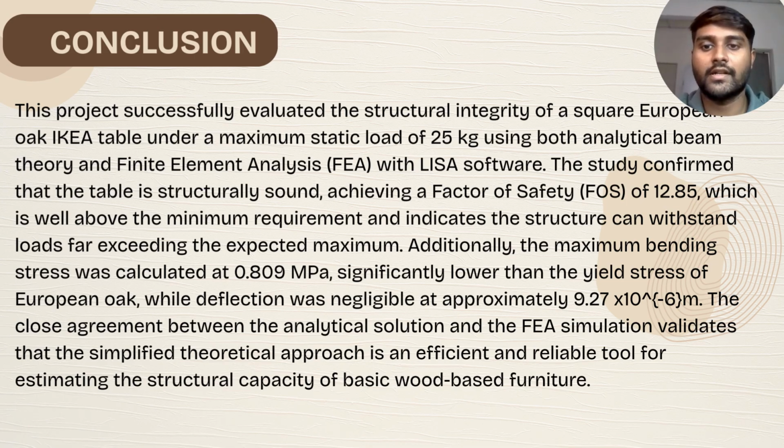In conclusion, this project verified the structural integrity of a square European oak table under a 25 kg load, confirming it is structurally sound with a high factor of safety of 12.85.